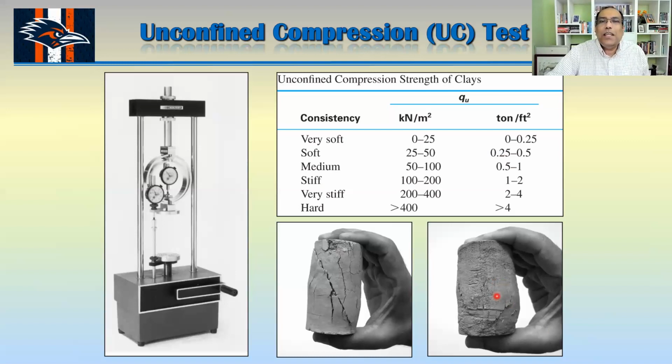In that situation, you just try to see how much shear stress you need to get 2% or 3% strain. That's basically your shear strength. Anyway, this is the unconfined compression strength of clay. We call that one QU.